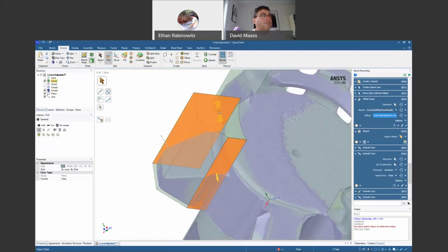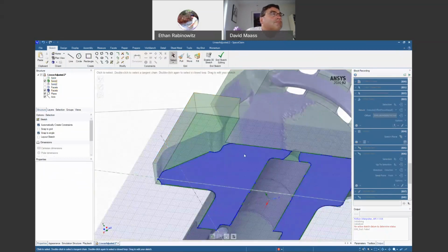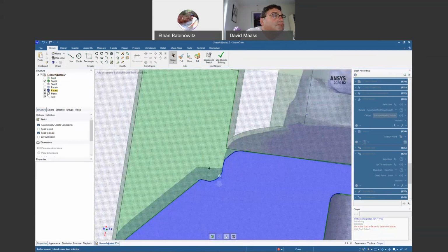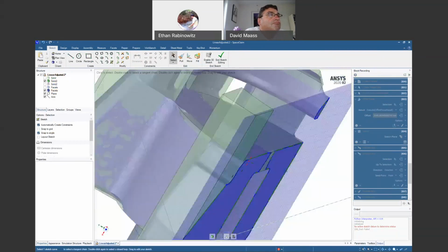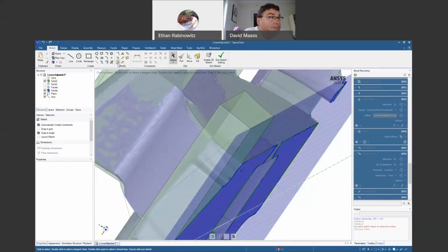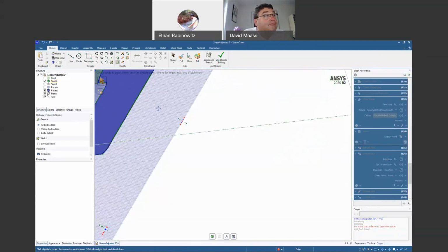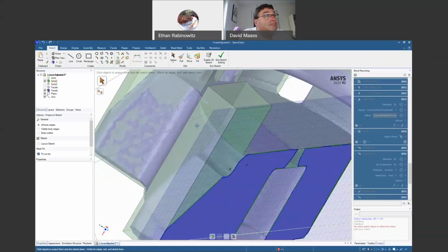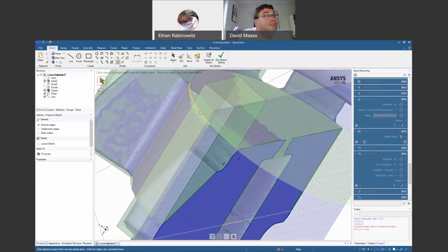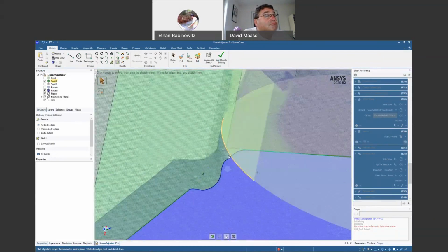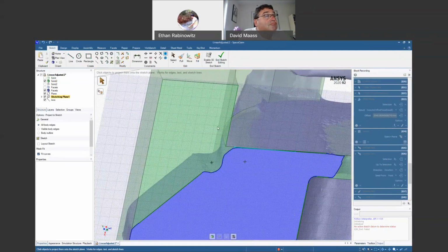And then I think last but not least, on this tab, we go into this cross section. And we want to do a cut through here that's going to conform to the cylinder that we have. So I can do a project to sketch, and in this case, let's see, what will let me project? I'm going to project that edge. Actually, I guess it's really just a continuation of this edge down.